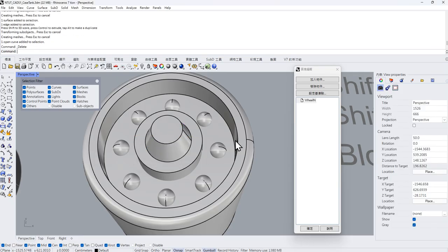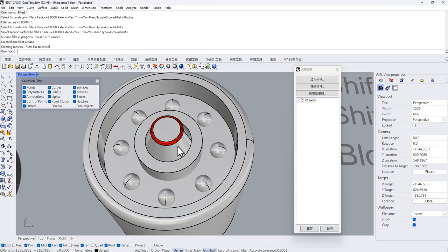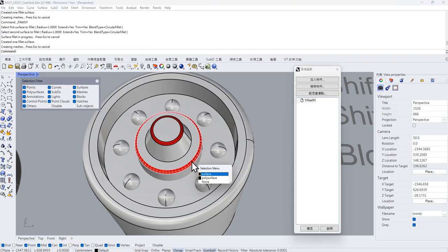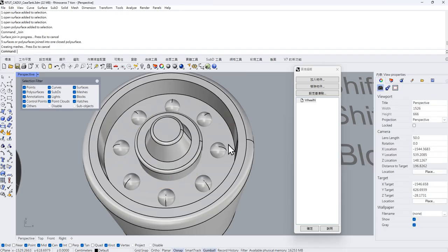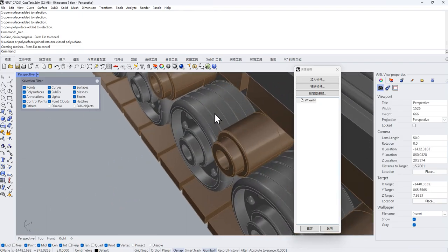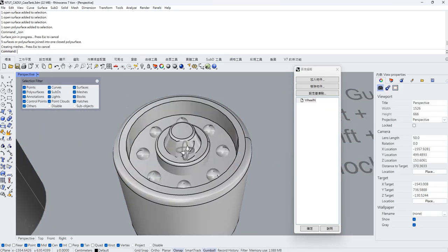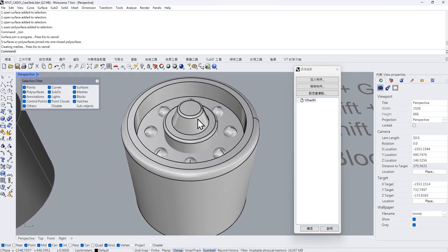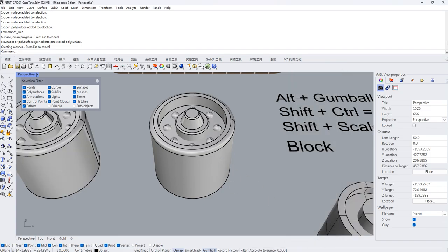Next thing I want to do the fillet surface again. Let's choose this one. And this time change the radius to 1. Fillet surface, add some more detail. And please remember to join them together, because for fillet surface, it will separate the object that you create. All right, so now we have that. How about the crease? For the crease part, I will stop right here. Give you some time to finish this part first, so that next time we can try to add some more detail. Okay.